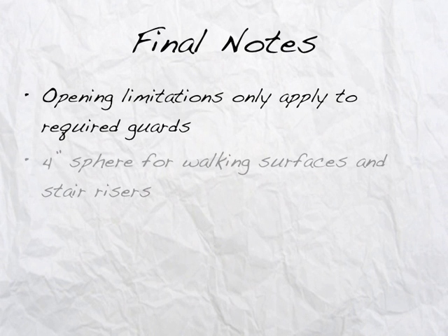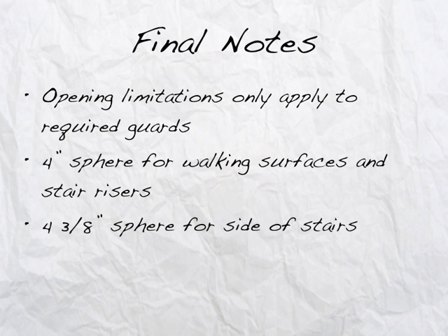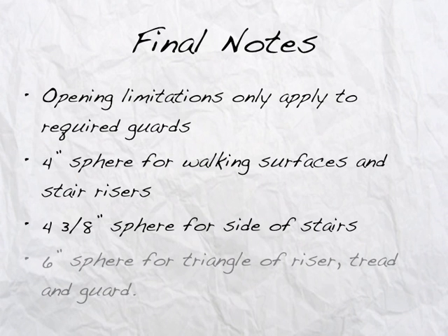No passage of a 4-inch sphere is allowed at walking surfaces and at stair risers. And no passage of a 4 3/8-inch sphere is allowed at the side of stairs. And no 6-inch sphere can pass through the triangle made up by the riser, tread, and bottom of the guard.